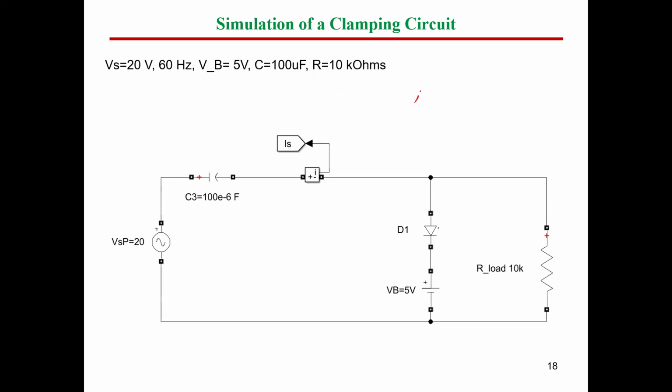The software here is Matlab, and the toolbox that will be used is called SimPower Systems. I will show you today how to use this toolbox in order to implement any electrical circuit to simulate the electronic components. So here in this example, for instance, we have a simulation for the clamping circuit.